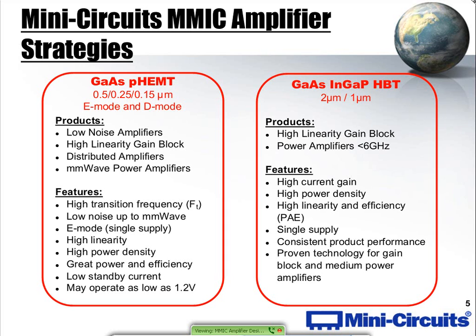In an E-pHEMT structure, if we use it in a single-ended or in a cascode design, you really have a very large 1 over F slope. And to control that, you need to put feedback in. And feedback is not so simple here because it has some negative effects on noise figure and IP3 and P1 dB.